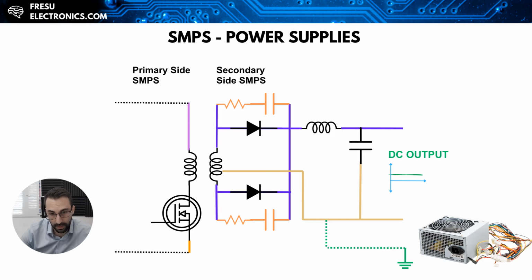And one of the possible and actually very effective solutions for these fast switching differential mode currents is to implement an RC filter across the rectifier. And this allows filtering out the noise of the differential mode currents. Unfortunately, the side effect of this technique is that the energy will now be dissipated through the RC filter, which also increases the power losses. And then the voltages and currents across the used device can also increase.